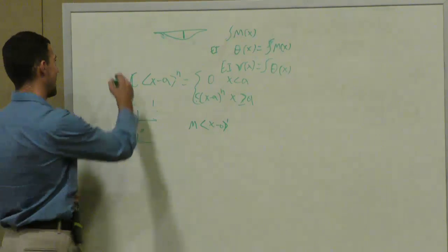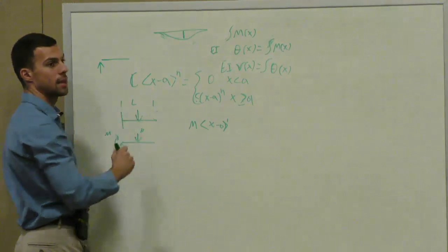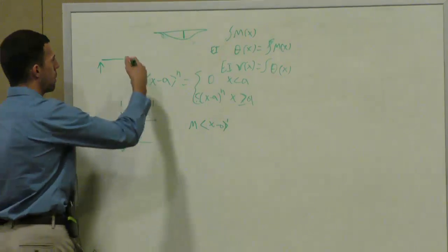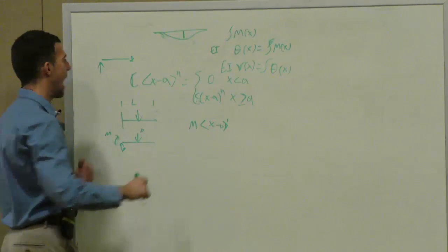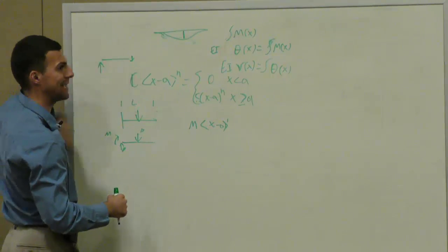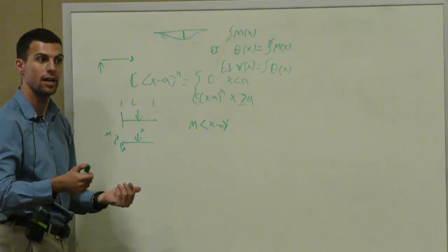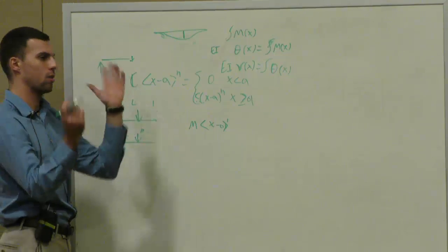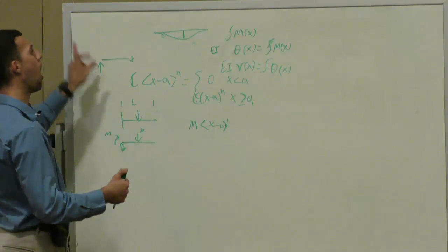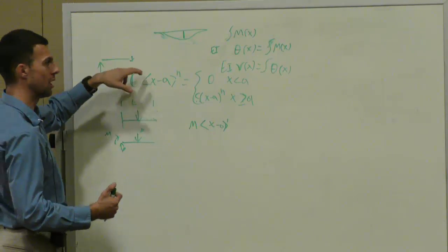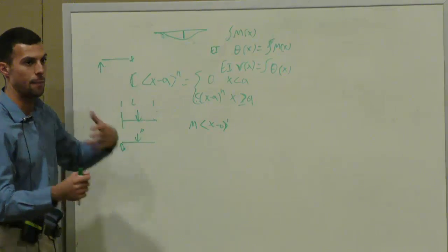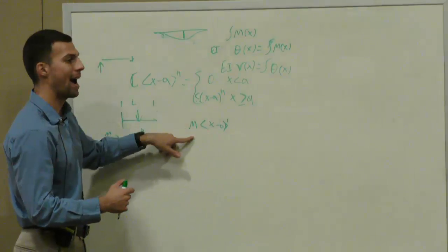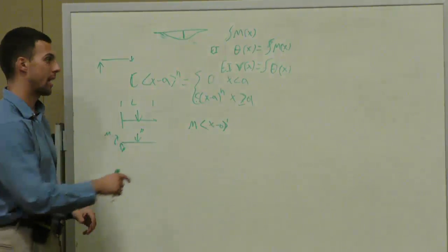And what you'll notice is upwards is the positive convention, okay? And that's because you're looking at the internal stuff, and so going from left to right downwards is positive, right? And so the internal moment that an upward force causes is downward, so this is positive. Does that make sense? So if the applied load is upward, the Macaulay function is positive, okay?